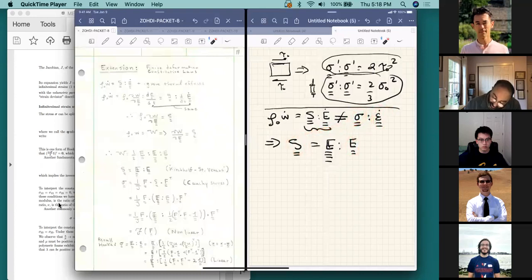So this constitutive law turns out to be probably the most commonly used, for example, in aircraft industry, cars, plates and shells, any kind of deformation where the deformations are just slightly bigger than 1 or 2%. People switch usually from the constitutive law that has to do with Hooke's law, which is shown here, and they replace it with this law.